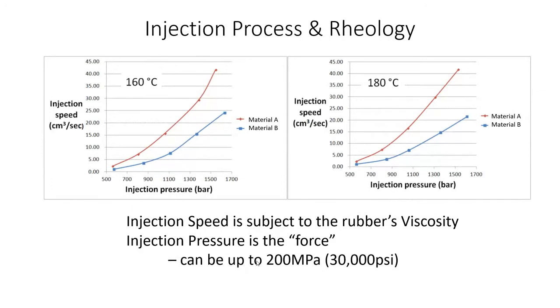So pressure is major, and the material's flow behavior is very dependent on that machine's performance. And so from the high view, we can see that if we're going to do a cavity design and we're going to use CAE, we really need to characterize the specific material we're using. We can't go to a standard library and use an EPDM formulation, even though we're molding a nitrile.